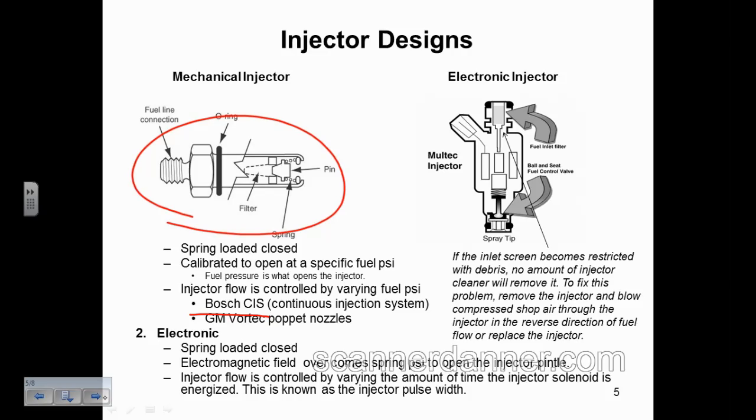I get that a lot. If you're going to fire all the injectors at the same time, aren't you wasting gas? The answer is no. What's controlling the fuel into the cylinder? The intake valve. And so on a TBI system, same thing, which cylinder's getting the fuel? The one that the intake valve opens. On a carbureted engine, which cylinder's getting the fuel? The cylinder that the intake valve opens. So we still have our intake valves that are controlling air and fuel into that cylinder, right?